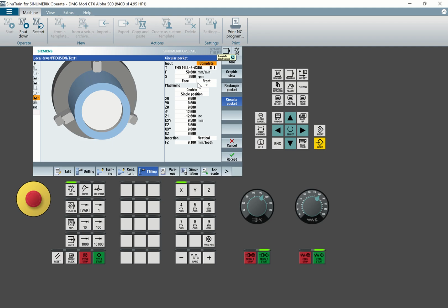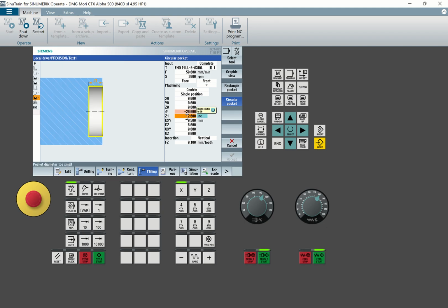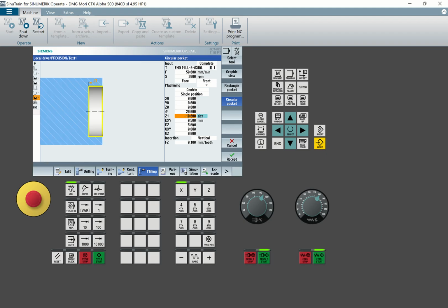Okay, no problem. And then I can come here, say the tool. I want to use Axial, centric. Make sure it's centric. It is only one point. The diameter that I want to put on this 36, I can put minus 20. Z to go inside the 15. That is minus 10. Then here I can go 5. Yes, this one change to absolute. The diameter, sorry, not minus, it should be positive. 10, then we go 5. Okay, I can just okay.